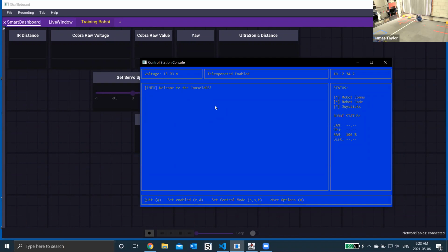And we are just direct connected to the controller via the driver console on the PC. So when you're in teleoperated mode, you can test, you can run, you can do different aspects. And then you'll notice that when you enable autonomous, if the code is running on the robot, it will run whatever autonomous code you have chosen here.